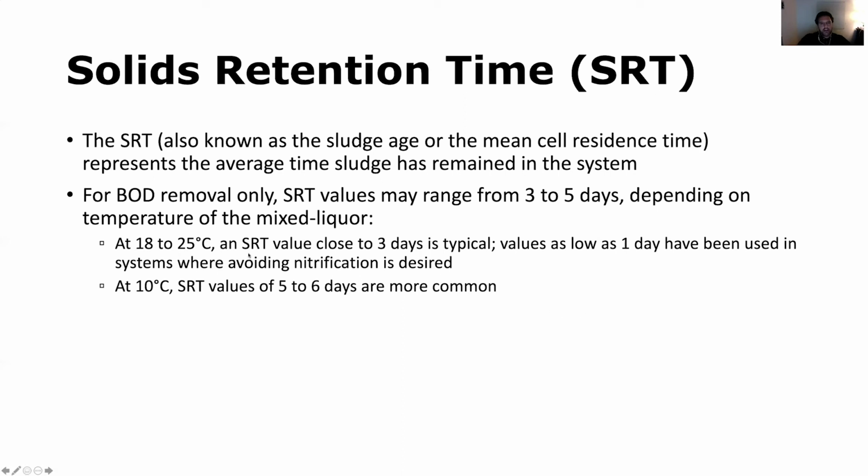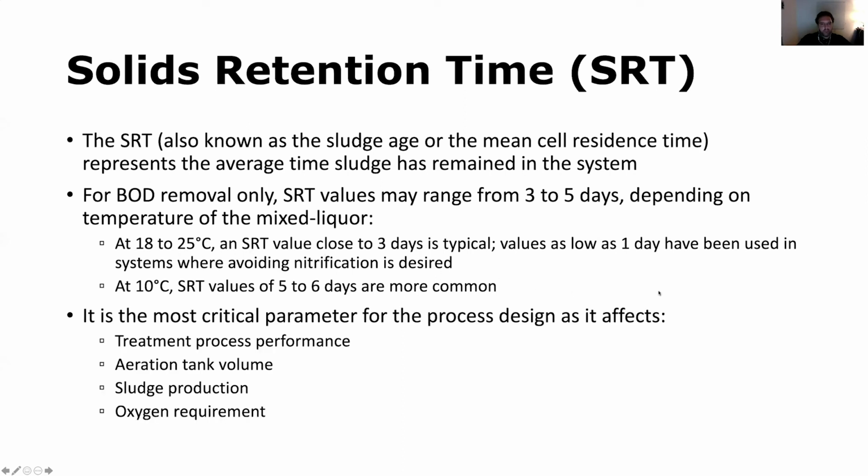All right, so depending on our goals, we're going to set an SRT value for our system. This is the most critical design parameter, as I mentioned, for process design because it affects the process performance, it affects the volume of the aeration tank, it affects the sludge production rate, and the oxygen requirements, all of which are related to the cost of operating the system.